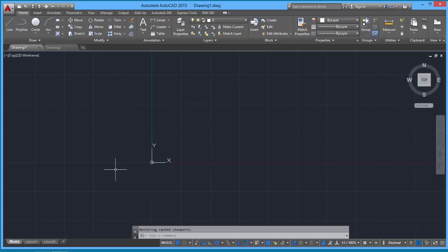All you have to remember is that when you're drawing something that's potentially going to be output at a big scale, i.e. 1 to 100, 200, 500, 1000, then it's going to be reduced by that scale factor. So don't draw detailed items because they won't view. If you've got things that are 1 to 10, 20, 50, or 1 to 1, 1 to 2, then obviously you can put more detail into the drawing. Okay, so the scale is important, but also the level of the detailing you draw is equally as important.